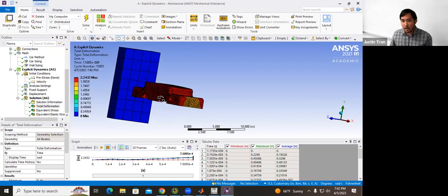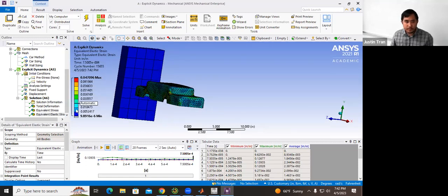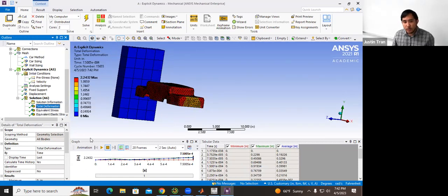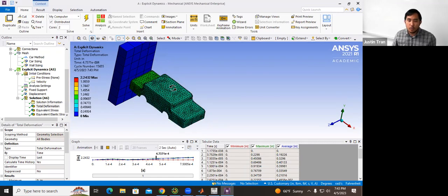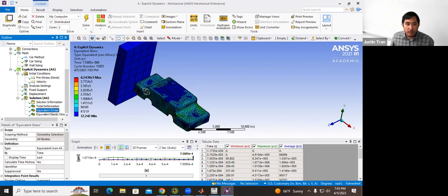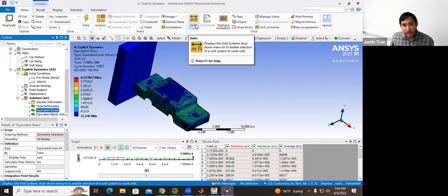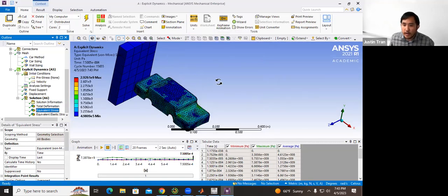If you want a better indicator of how the car is actually deforming and changing shape, strain is going to give you a much better result than the deformation. That's why the deformation looks a little bit strange. If you play the animation, the whole car changes colors together, so you don't see finer gradients, except for this weird jiggle going up on the top here. So for this activity, I would recommend that you look at strain rather than deformation. Stress as well. In order to get the stress in megapascal, you might have to change these units, and you can do that as well.